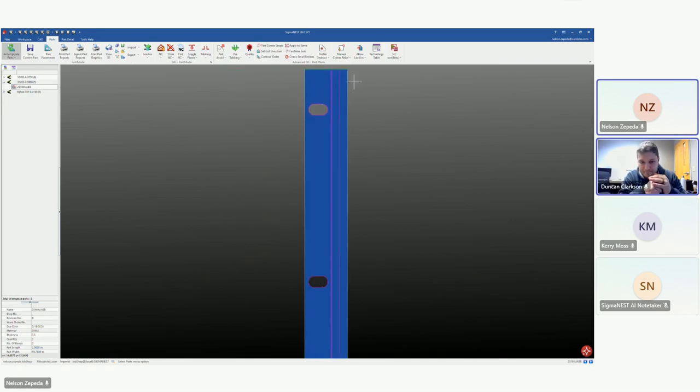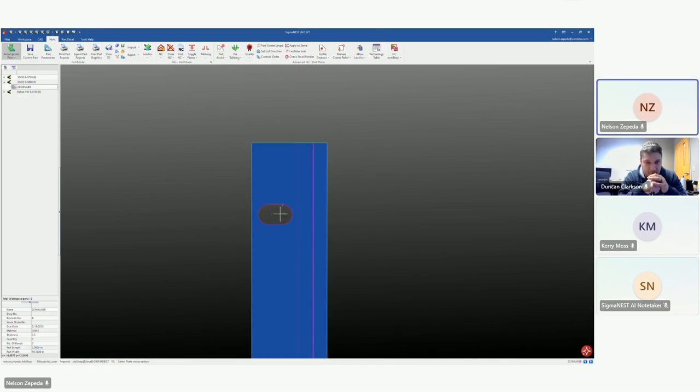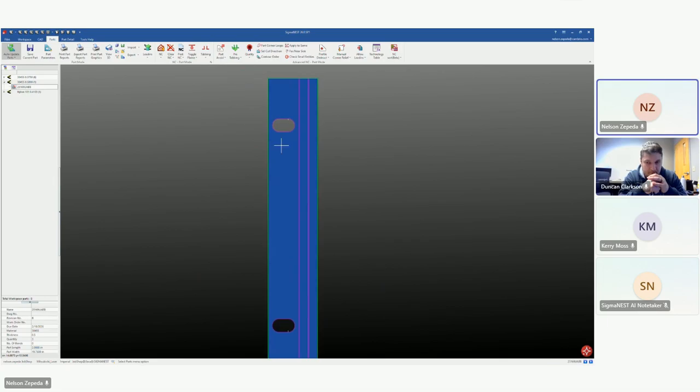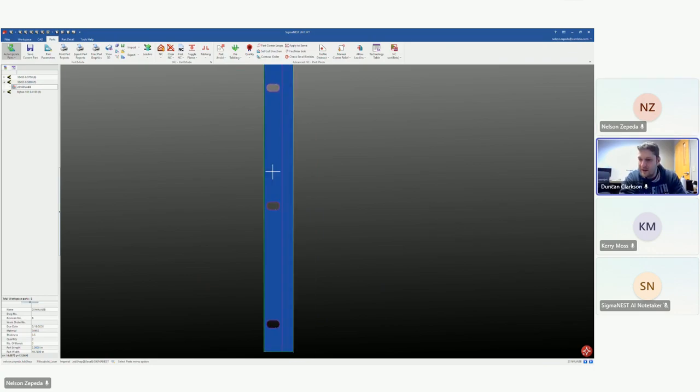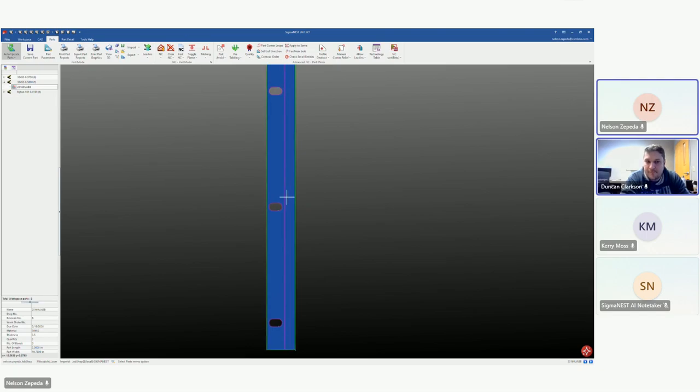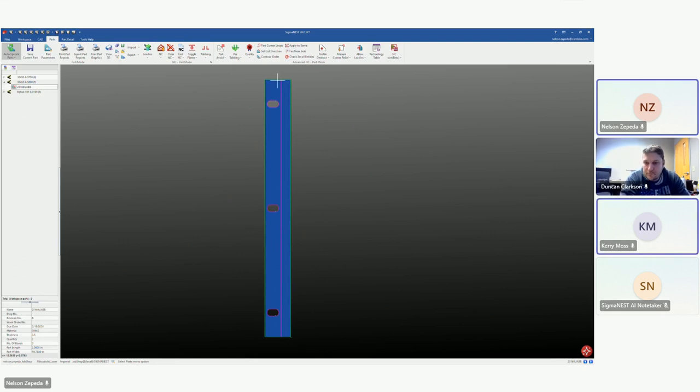All right, so what was going on here? I have what looks like some bend lines came in maybe. I'm not entirely sure. Shouldn't be any. These are bend lines, sketches. But there is a milled edge on there, so it's cut out, so that's probably what this milled edge is then. Yeah, so it comes in with the geometry there, and then in SigmaNest, the way it's reading it, it's going to try to etch or mark these, but I can delete them.